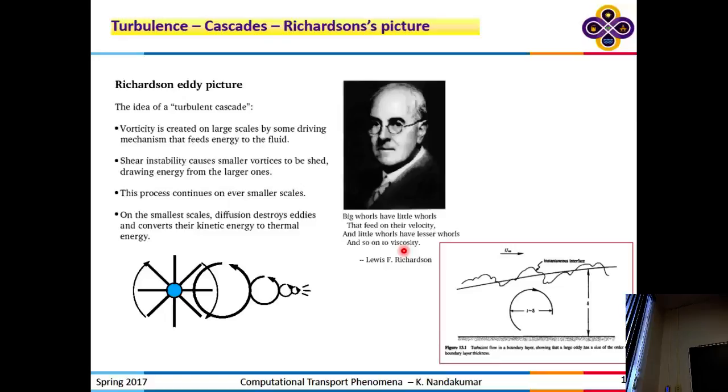Once you understand that mechanism, then you can say, okay, I'm going to look at all the large-scale structures that form above a certain scale. And what happens on the scale below that, I'm not able to resolve, so I'm going to model it. This is the basis of something called large eddy simulation, which tracks the dynamics of larger eddies.